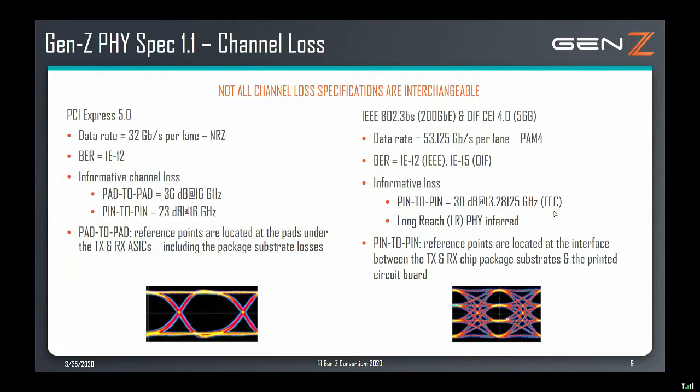Good question. They are different applications, so it's kind of like comparing apples and oranges, where PCIe is really targeted at a prescriptive space, and it has a use case for endpoint topologies, like I was talking about earlier, where you would want to connect to a processor directly, or memory directly, or NVMe. And then Ethernet has a broader scope, so it has more topologies that it can support. So neither of them is better than the other. PCIe has some advantages because you could make the case that it has a cheaper PHY because it has less equalization than the Ethernet PHY. So there's advantages to both.